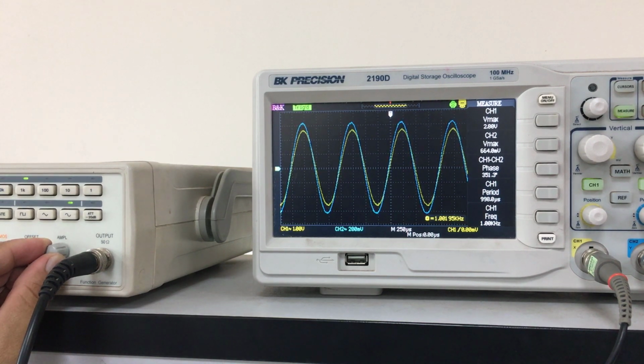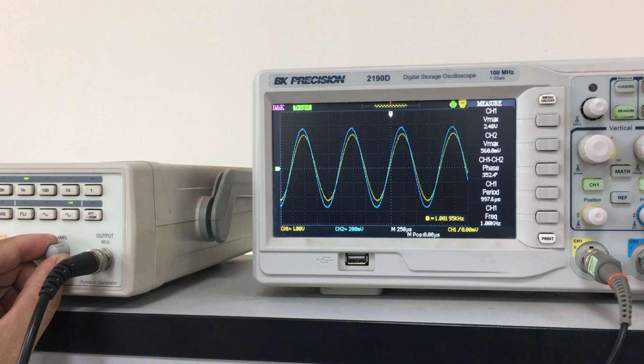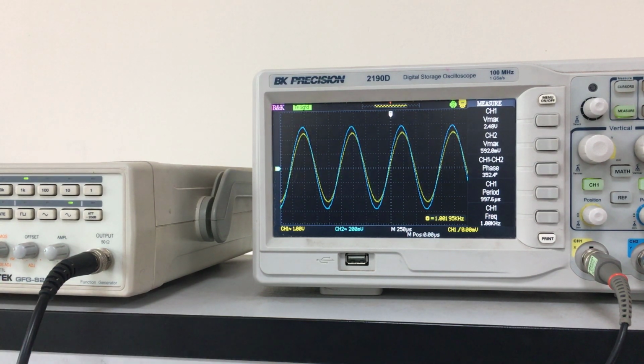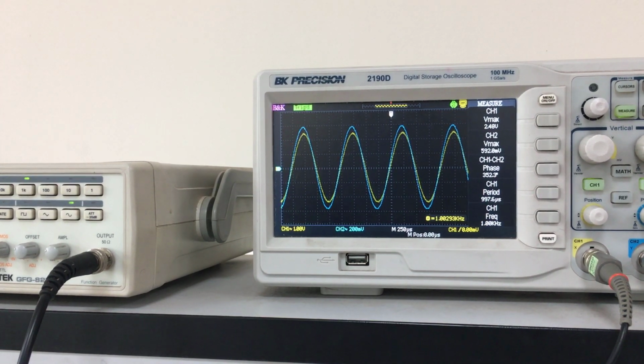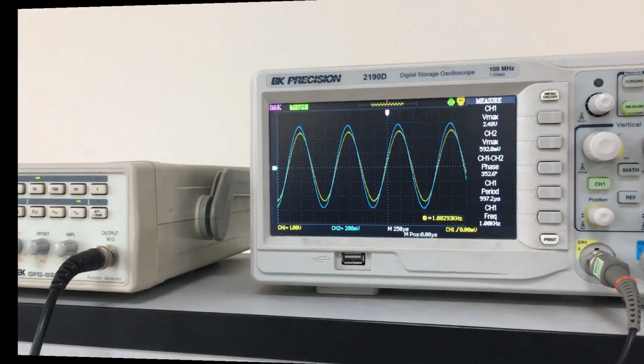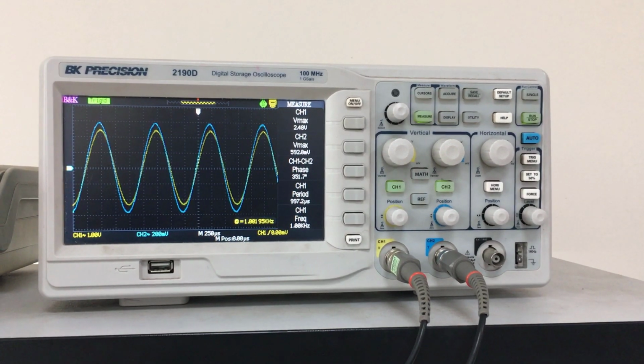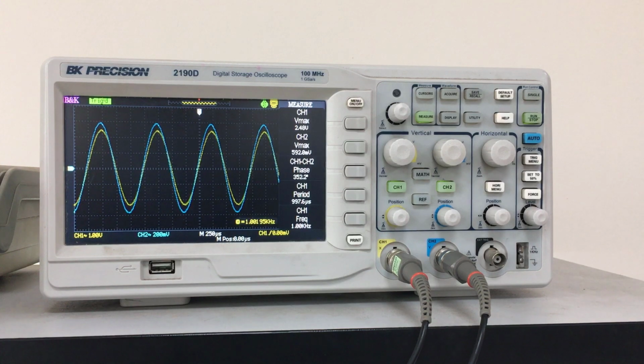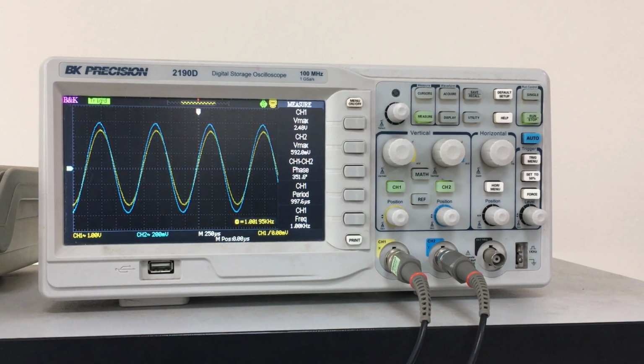So channel 1 max, which is connected to our source, should be 2.48 volt max. Okay, so we have set 2.48 volt max in channel 1, which is our source, and we do not have any control over the phase of the input, so we are just setting the input voltage.